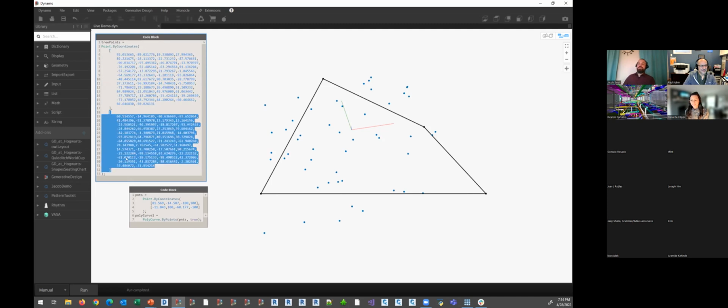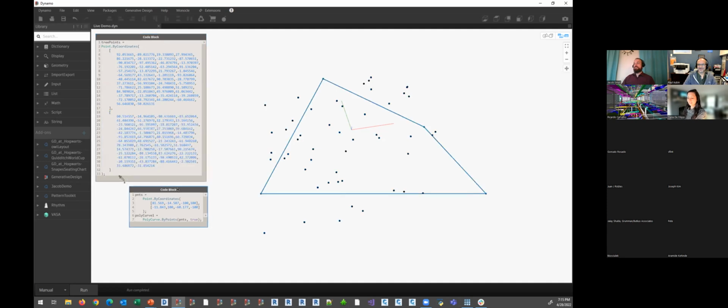This is basically what your surveyor is going to do when they pull up a list of trees. There's a tree here. We've got a point, its coordinates in X, Y location, maybe Z if they're smart about it. And then that content gets brought over to create blocks in Civil 3D, right? I'm just cutting out the middleman. And then I've got another code block down here, which is going to generate a series of points. And then I'm going to use those points to generate a polycurve, just like I had a site plan.